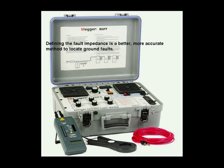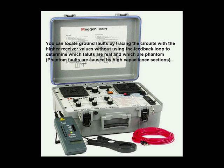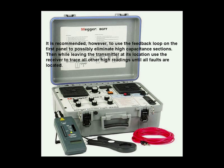Defining the fault impedance is a better, more accurate method to locate ground faults. You can locate ground faults by tracing the circuits with the higher receiver values without using the feedback loop to determine which faults are real and which are phantom. Phantom faults are caused by high capacitance sections. It is recommended, however, to use the feedback loop on the first panel to possibly eliminate high capacitance sections. Then, while leaving the transmitter at its location, use the receiver to trace all other high readings until all faults are located.